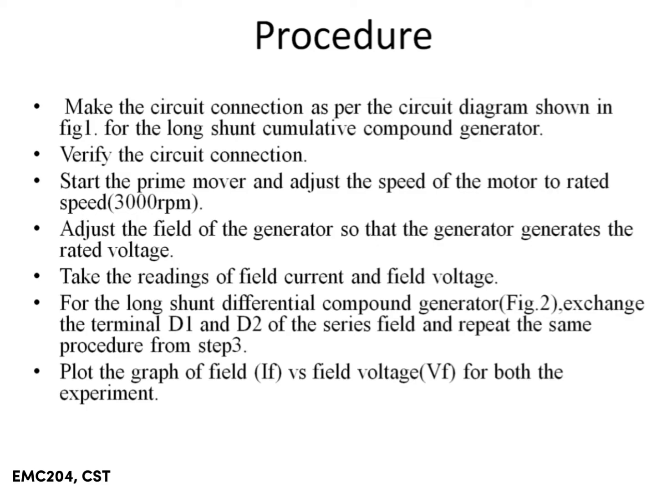Exchange the terminals D1 and D2 of the series field and repeat the same procedure from step 3. So finally, plot the graph of the field current IF versus field voltage VF for both experiments. These procedures are explained in more detail in our experiment, which you are going to see in the following.